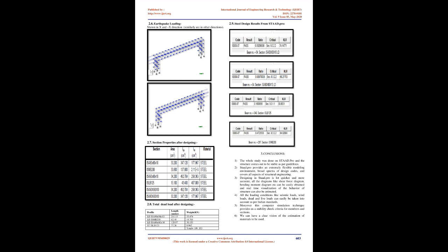1. Span equals 30 meter. 2. Clear walking width between main girders equals 2 meter. 3. Clear height of bridge equals 1.8 m. 4. Type of truss configuration equals Pratt truss. 5. Plate thickness equals 0.02 meter at bottom and 0.01 meter at top. 6. All members are of mild steel, angles and plates. 7. Site location equals J and K, earthquake zone V.